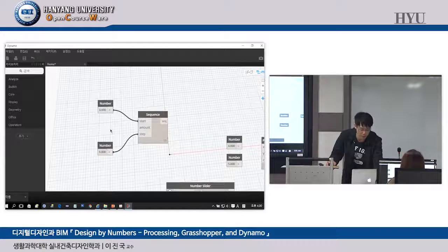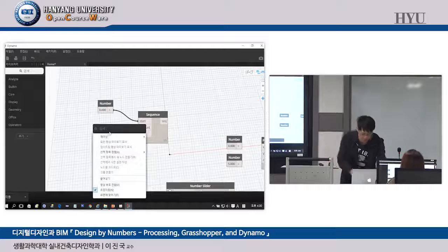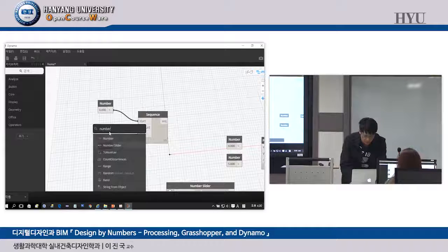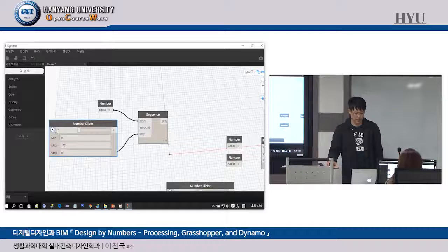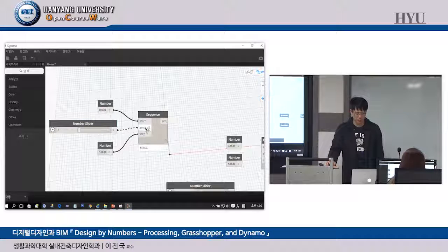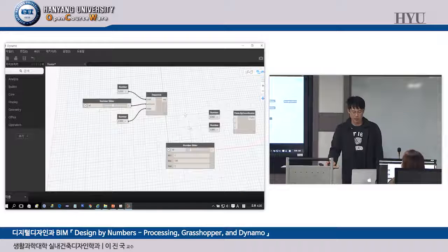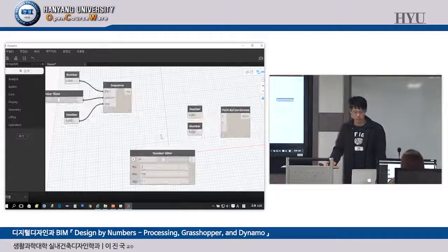And for the amount, let's use a number slider, with step 1, minimum 1, maximum 100. So this one can be the amount, with a default of 55, 41, whatever it is.